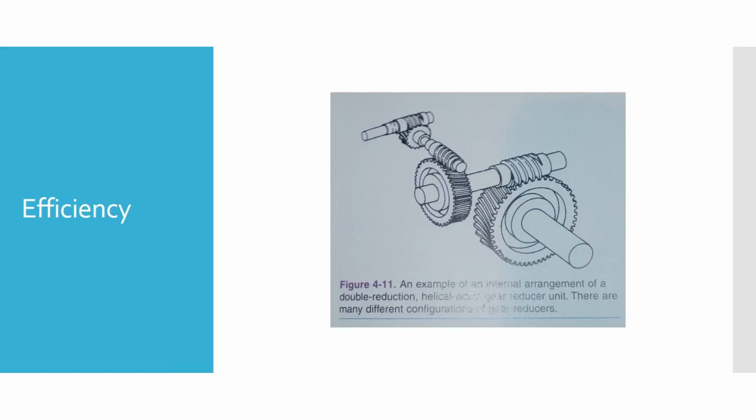A wattmeter measures the instantaneous power used in a circuit. A watt-hour meter measures the amount of power used in a circuit over a period of time. Efficiency is expressed as a percentage and indicates how well one form of energy is converted to another form of energy. Efficiency is equal to the power out divided by the power in.